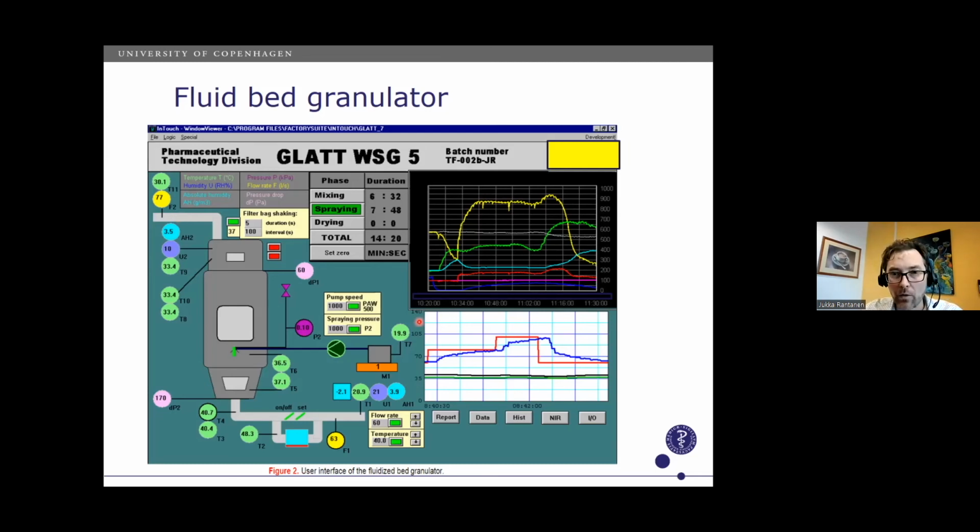And typically one granulation will look something like this here in this corner of the user interface. What we can see here is a time series of these measurements, and we can see that during granulation we have first a drop in the granule temperature, and then a slight increase, and then some fluctuation, and then also some decrease at the end of the process.